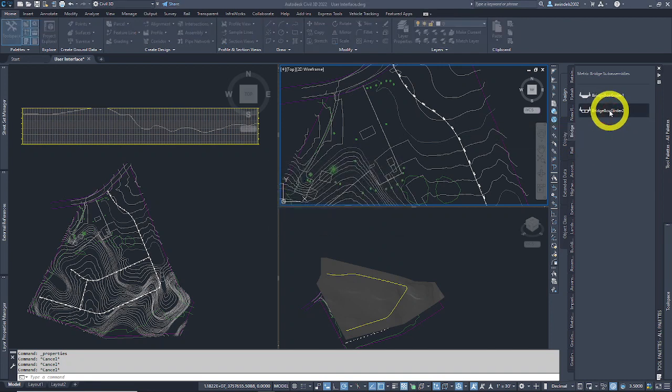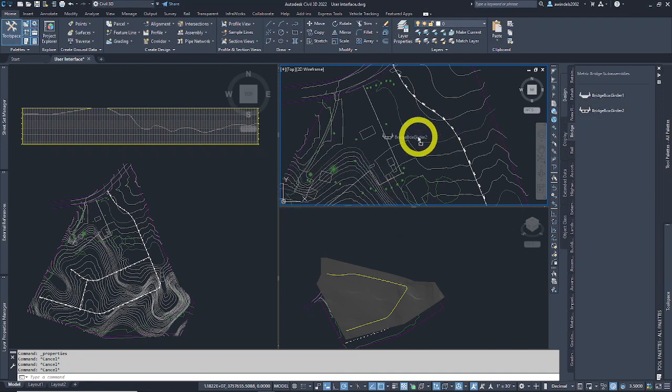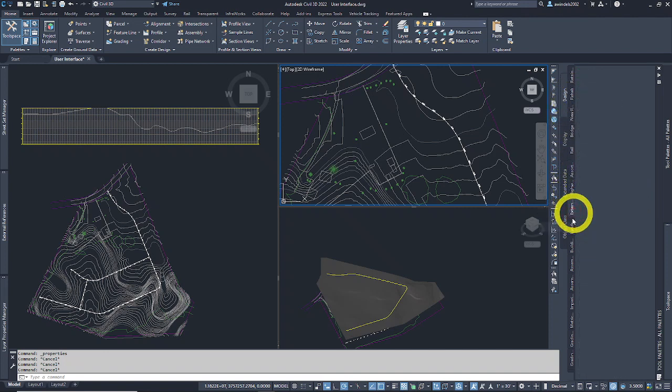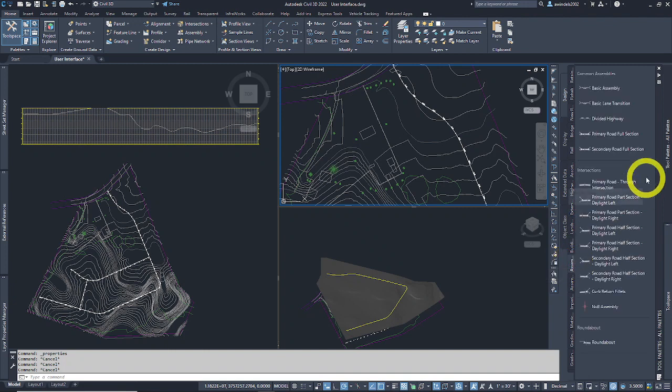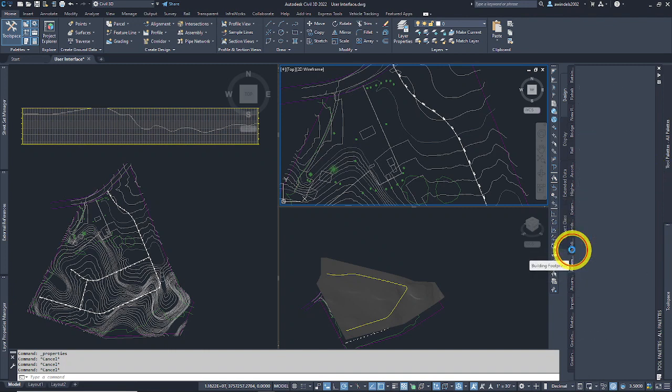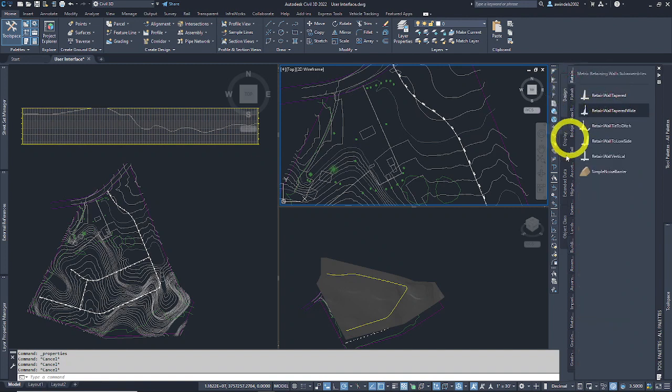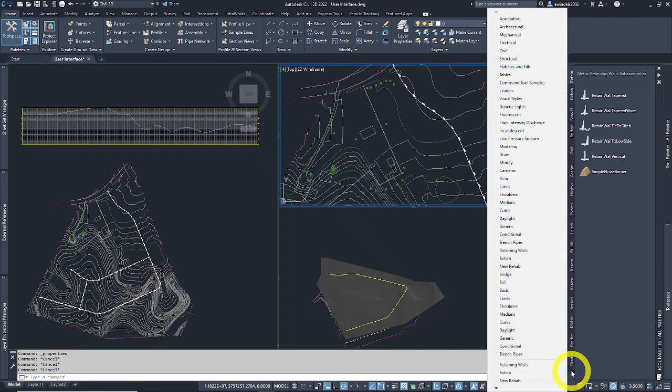We have a box girder here we can drag in and add to an assembly somewhere. For example, a box girder bridge section or some rails. Or we have highway signs. We have some road cross sections here. We have some building styles that we can add to sites. All kinds of stuff. A lot of the main ones, if you right click down here, very close to the bottom, you can see how many different tool palette areas there are.